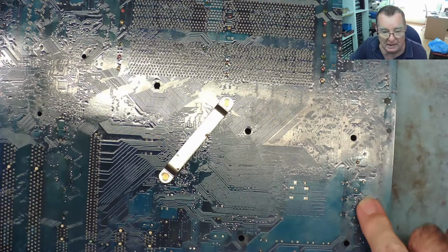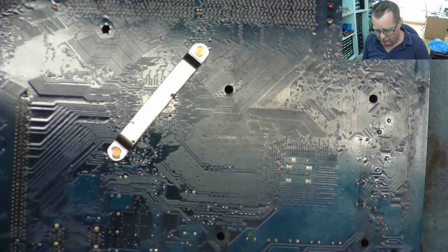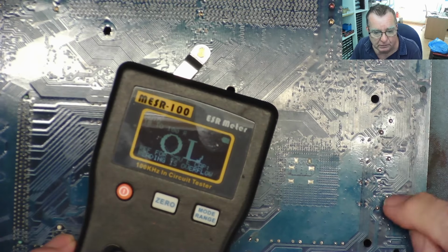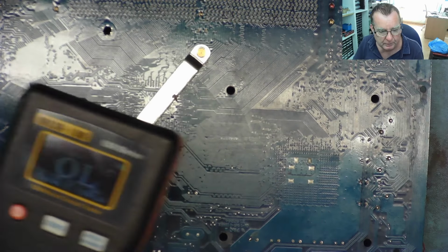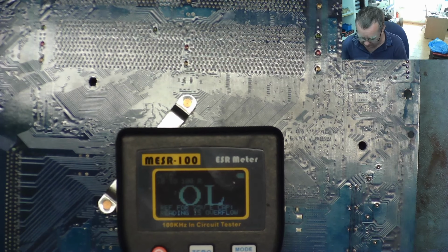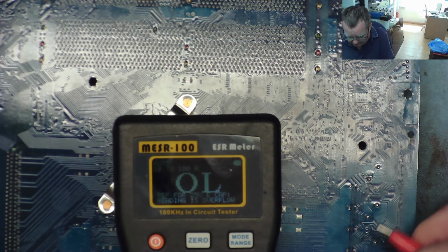And the way we do this, I'll show you first and I'll explain how this works, yeah? So these are the inductor coils. I'll zoom down a little bit so you can see it a bit clearer. Okay, you can now see 1, 2, 3 inductor coils, and the other ones are up over here just off shot, yeah. Let's see if we can find the short circuit one. So what I'm going to do is measure with the ESR meter across the inductor.